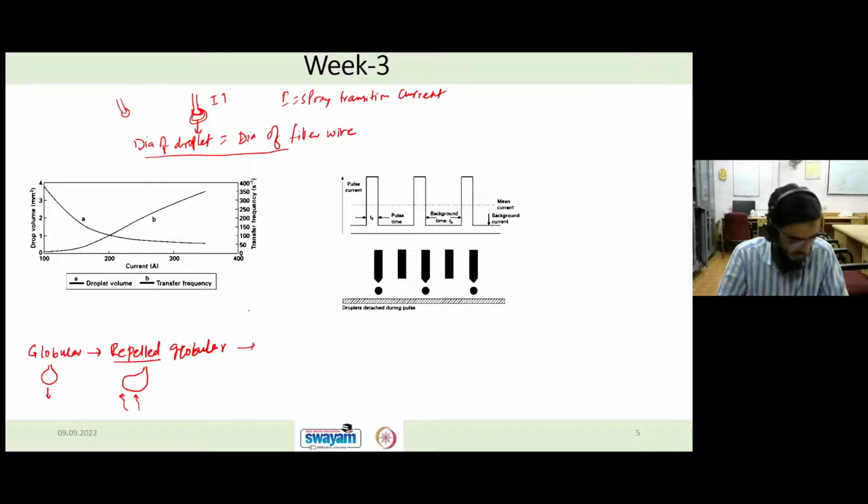Now if you further increase the current, the metal transfer mode will convert into spray mode. There the other forces, that is plasma jet forces and Lorentz forces, which assist the metal transfer, will be very high, and you will get spray mode. Very small droplets get transferred, and we can control it like one pulse per droplet, as we'll see in the next slide. Then if you further increase the current, it will go into jetting spray.